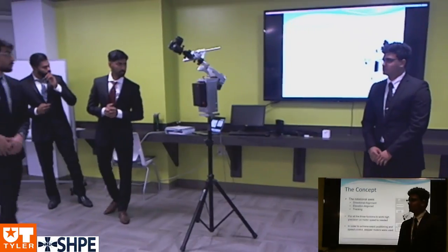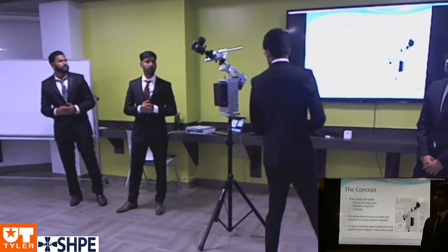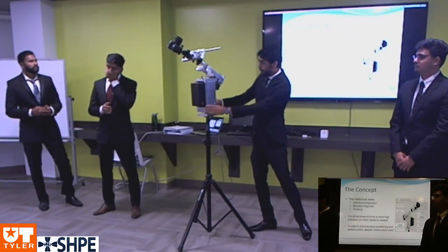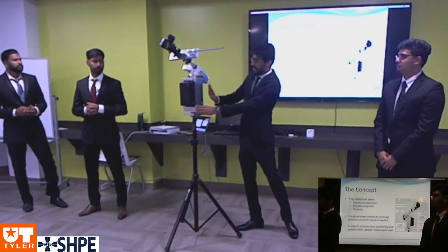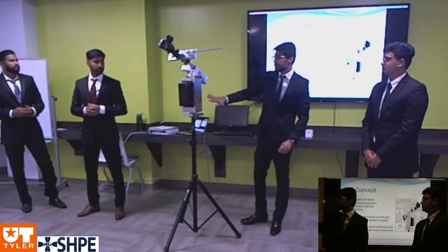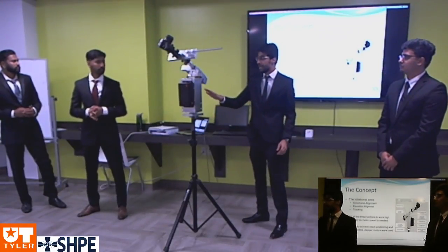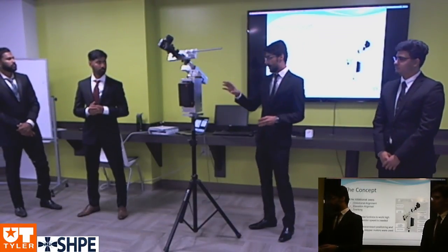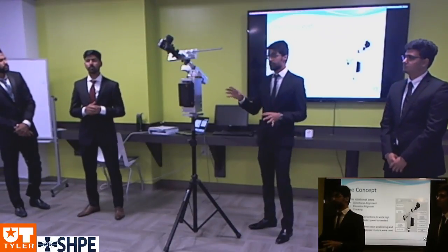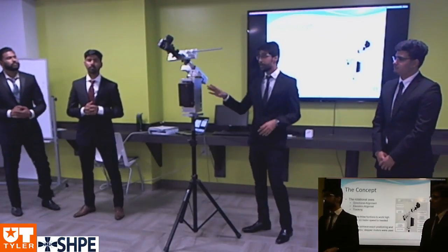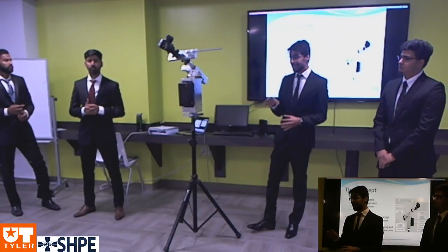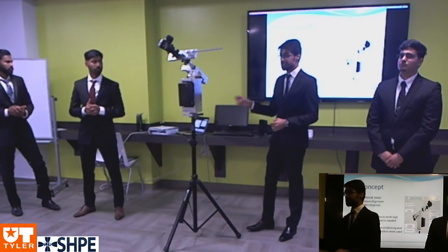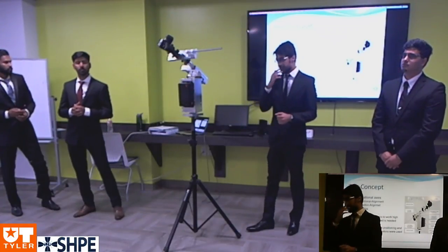Okay, here is the concept of our project, and we actually have 3 motors connected to the project. In the back here, we have motor number 3, and motors number 1 and 2 are actually inside the box. Motor number 3 performs the tracking and has a gear ratio of 100:1. There is a gear attached to it to help rotate the tracking axis with the use of a worm gear assembly to further increase the gear ratio. We need this high gear ratio to achieve an extremely slow rotational speed to match the Earth's speed.